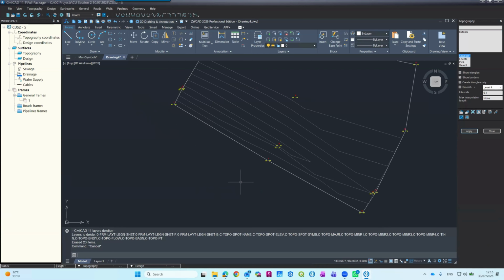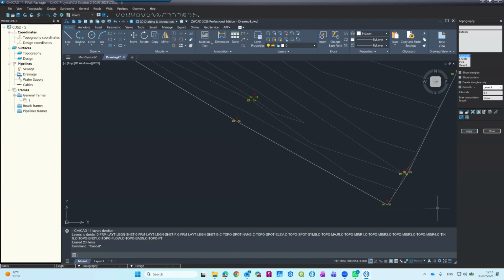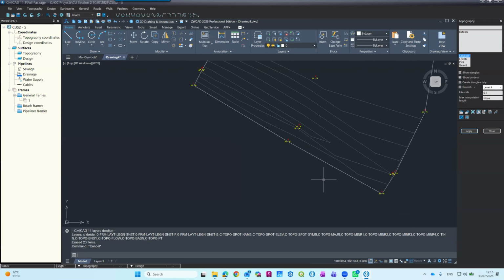Correct. So this is better, but I still see some problem here. The sidewalk is supposed to have, look, this is all 101.5, and all of these are 101.3. So there's a 20 cm elevation between these two, but the lines are not straight. They're supposed to be straight. Let me try to draw, I was expecting to see straight lines like this as my contour lines.